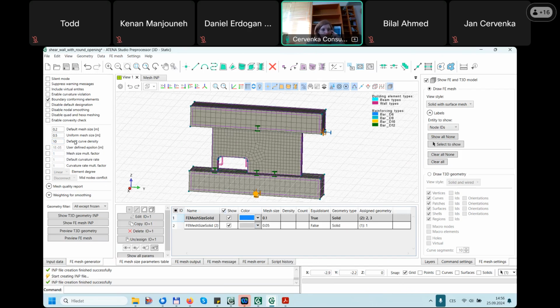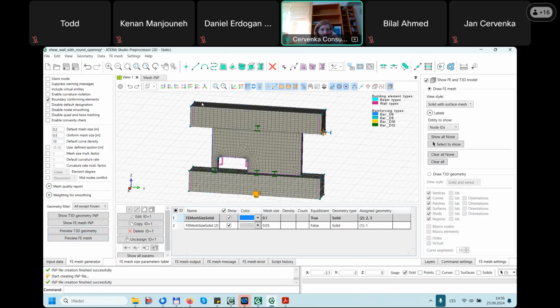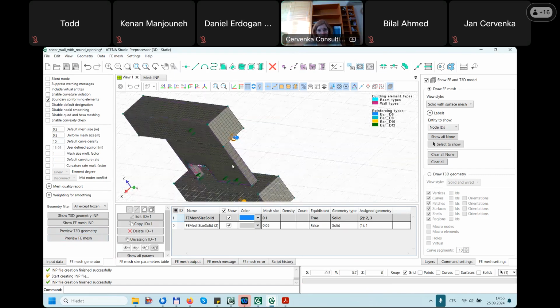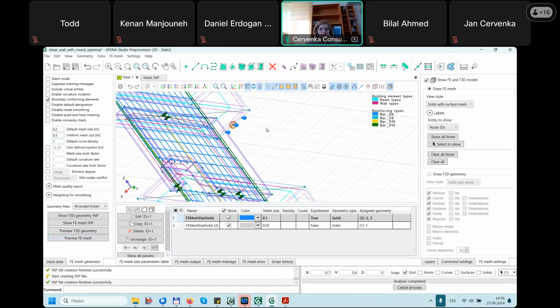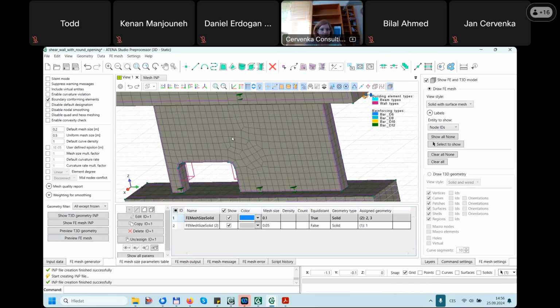So this part will be applied again only on the pieces where it makes a smaller mesh than defined specifically locally. So when I define it in here, it will change along the smaller parts of the geometry. So when I go back to number 1, it's according to these local settings.